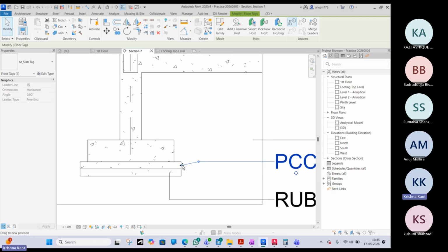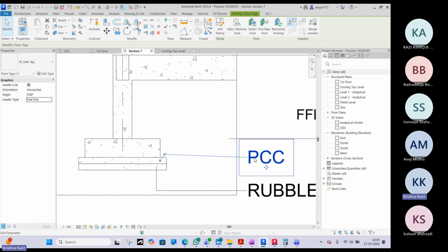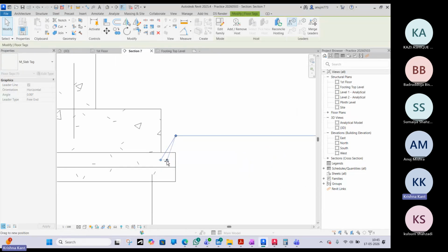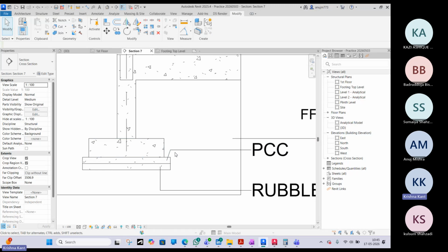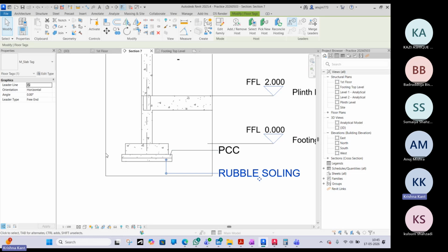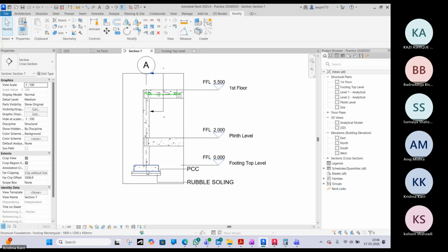Once you do free end, you have the ability to change its exact location. Otherwise, it's not easy to edit like with the attach end option. Okay. So if you want to edit it, make sure you change this to free end. Understood everyone? Yes, sir.